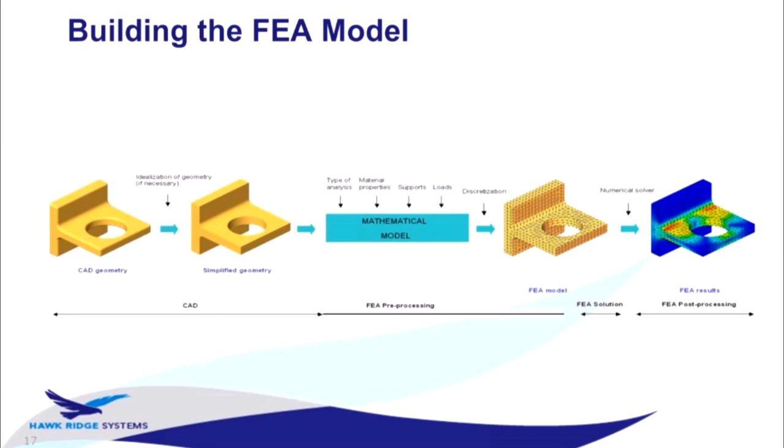So when you're looking at the analysis process from start to finish, it often involves a little more than what we talk about within the simulation tool. And generally, we start every analysis process with some sort of geometry. Right? It might be a production model that's being developed to develop the manufacturing drawings. It may be some dummy geometry that's been developed only for FEA. But an important first step is to consider a simplification step.